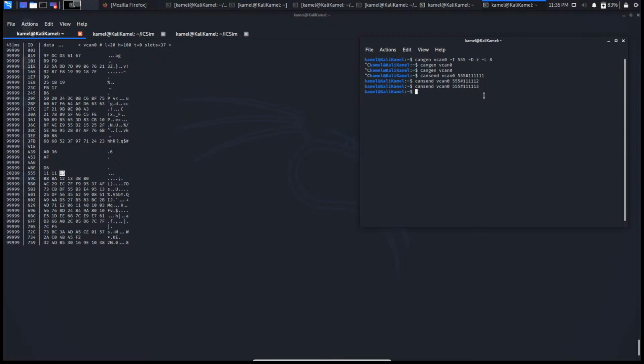It's helpful because sometimes you have a single CAN frame that you're watching, and you want to see which bytes change when the car performs certain actions. Maybe you want to see, all right, which byte changes when I turn on the turn signal? Which byte changes when I unlock the door? So on and so forth.